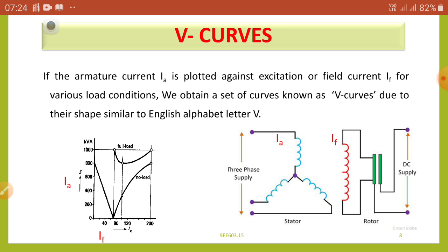Note that down. Now for the third reading, further increase the field current on the rotor side by changing the rheostat. In this case, 0.4 amperes IF. Correspondingly on the stator side, note down the ammeter reading and power factor meter reading.